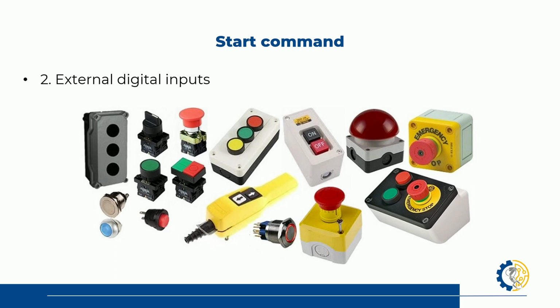Why? If the button is normally open, it means that it's waiting for a signal for it to close. So it's important that if I'm going to connect that signal externally, it needs to be external. And if it's a stop, it needs to be normally closed.